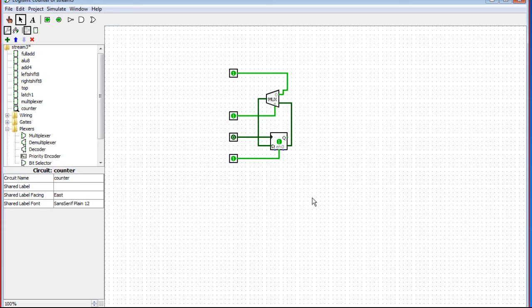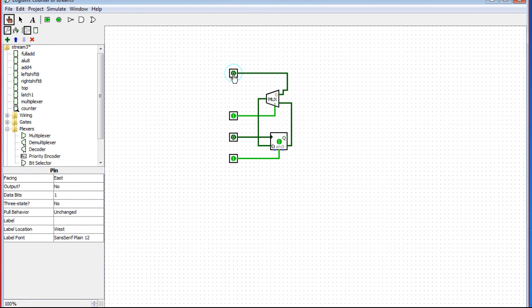Wait, I forgot to ask, Papa, are you lost with the toggle flip-flop? I have no idea. Okay, that's fair. Let's go over it once again, a little more gently. So, the enable input: when enable is 0, no matter what you do, it's not going to change, right? Okay. That just disables the changing of the flip-flop. Now when enable is 1, we can change it. Now there are 2 modes for this flip-flop.